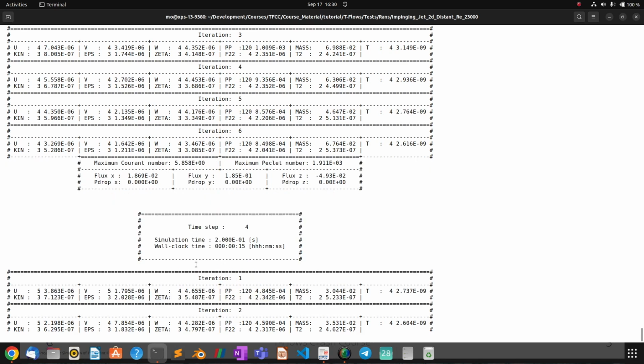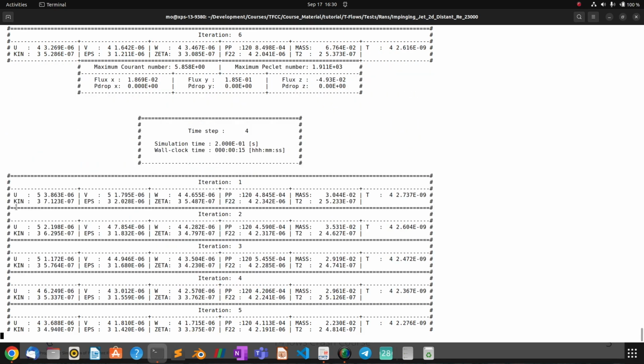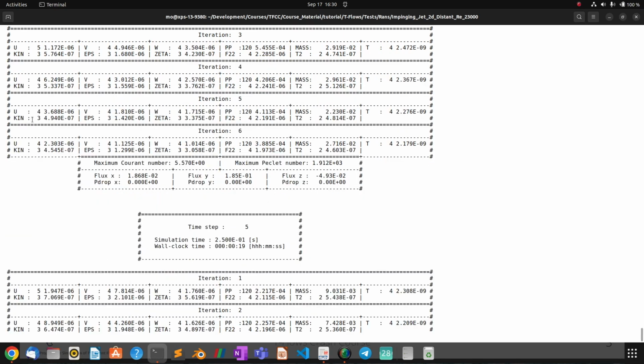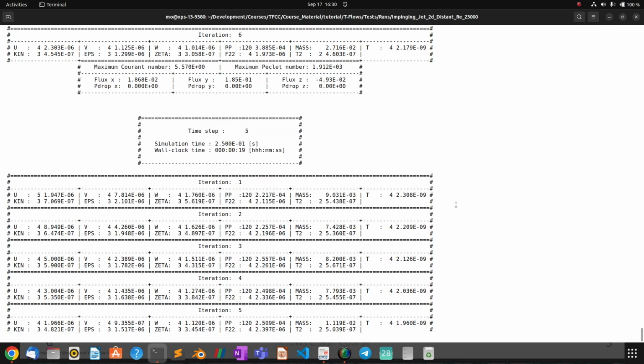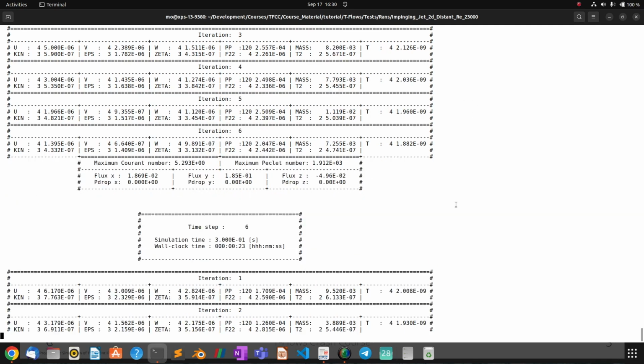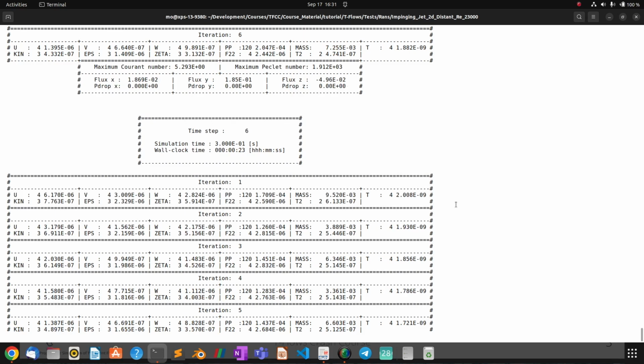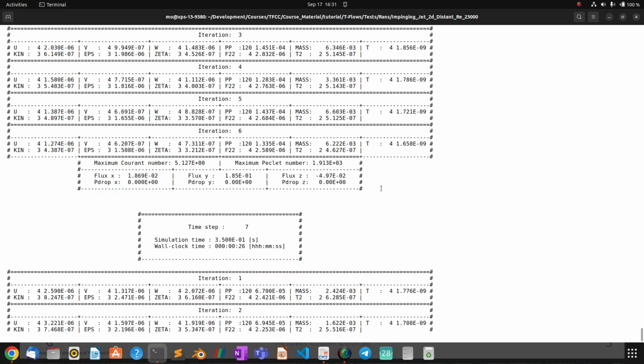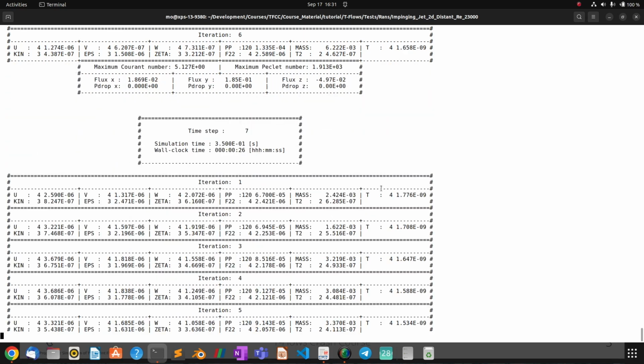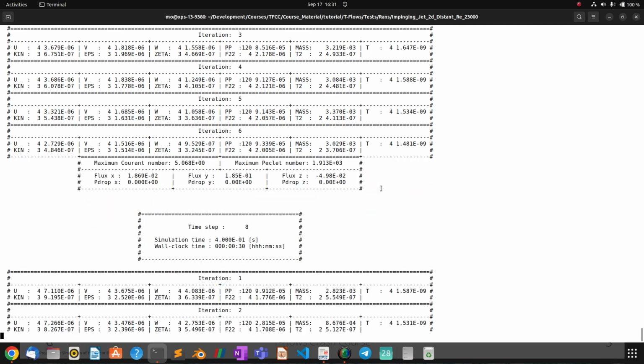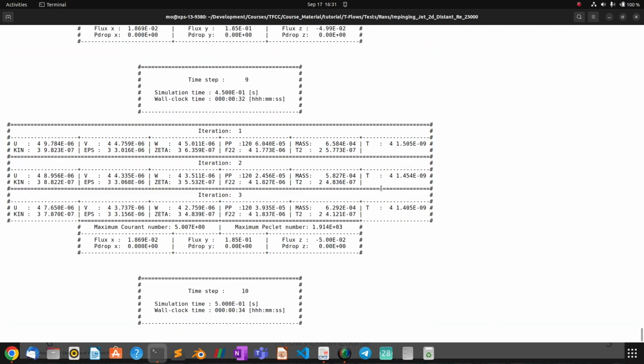You can see already all the residuals that I talked about before: U, V, W, and then you have k, epsilon, zeta, f, because those are the transport equations that you're using in this problem. So if we can add a new tab here, I can show you a couple of other things while the solution is progressing. We can press Control-Shift-T to open a new tab for you. And then we can tail the solution like this.